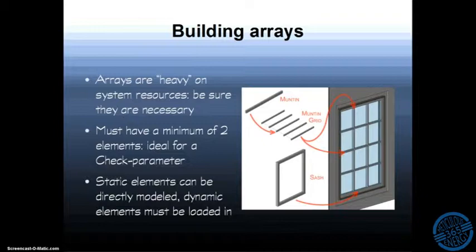If you attempt to dimension or align elements within groups to elements outside the group in any manner that you would normally use to control normal family geometry, those efforts break. The array becomes entirely uncontrollable from a parameter standpoint, the way you would expect other sweeps, extrusions, and things to be controllable via parameter.